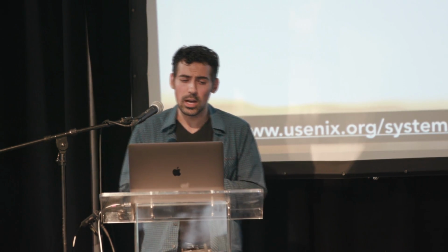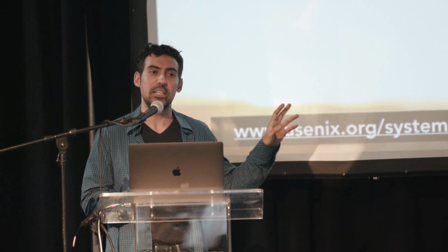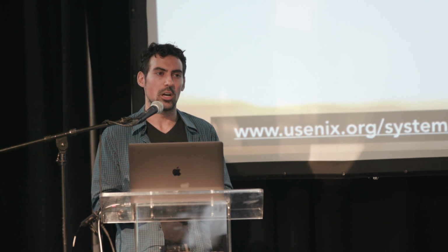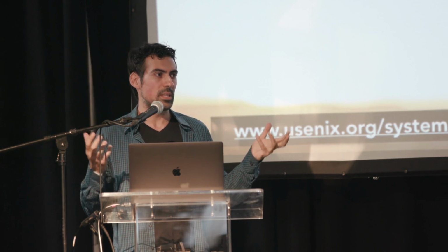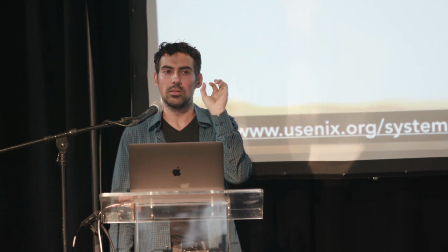So just to talk about some of the other cool physical phenomena around fault injection. A really cool paper on attacking drones and controlling drones using ultrasound. All of our drones have IMUs, right, these are accelerometers, gyroscopes, magnetometers that are measuring, okay, where am I? The nice thing about a drone, the reason it's so cheap, is that there's really just a little microcontroller and an IMU that's controlling everything.